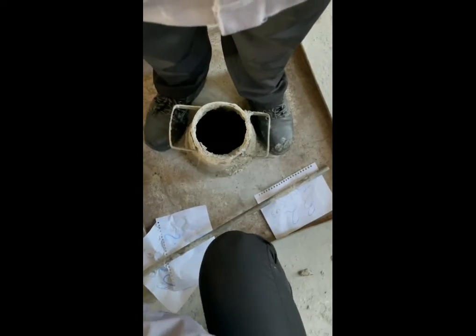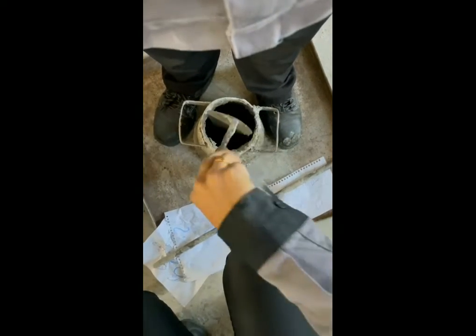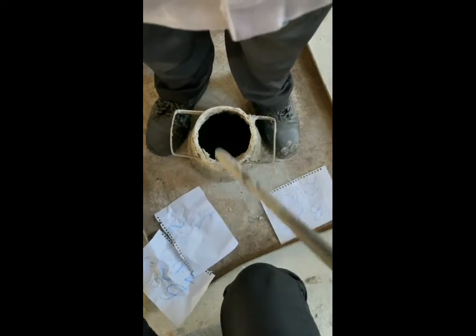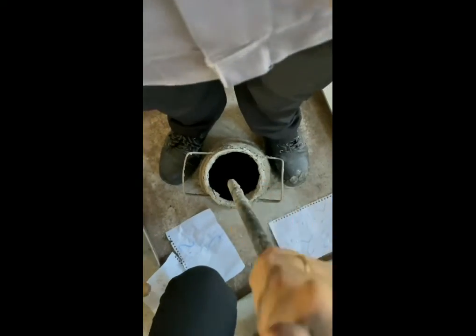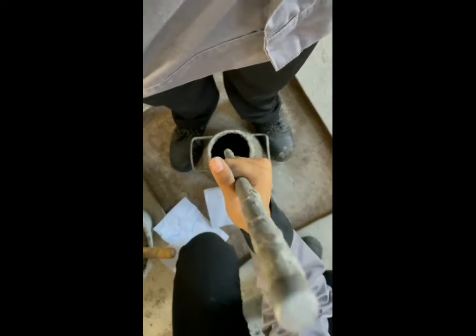For the slump test procedure, the slump cone shall be in the form of a frustum of a cone having the following dimensions. The internal surface of the mold was cleaned thoroughly and placed on an aluminium tray with a smooth, horizontal, rigid and non-absorbent surface. The mixed concrete was placed in the clean slump cone in 3 layers, where each layer was tamped 25 times using a tamping rod.